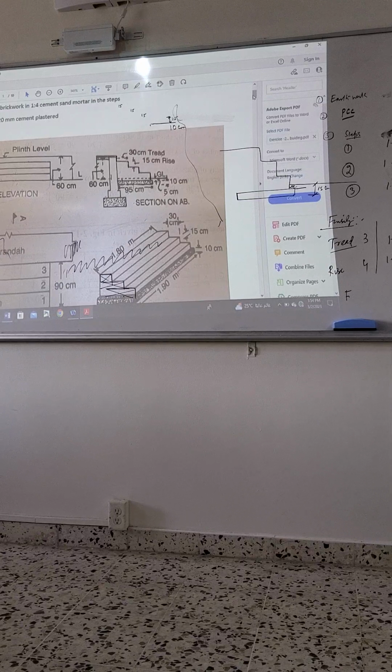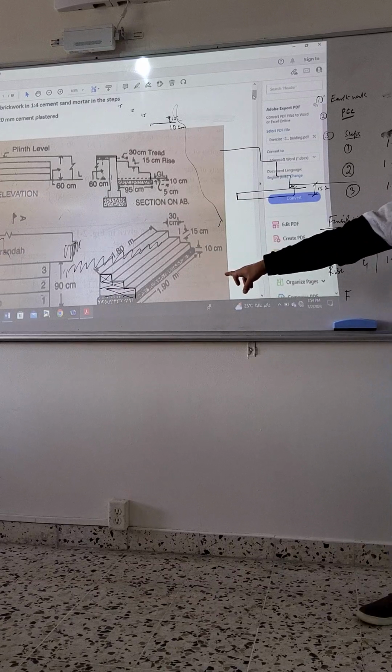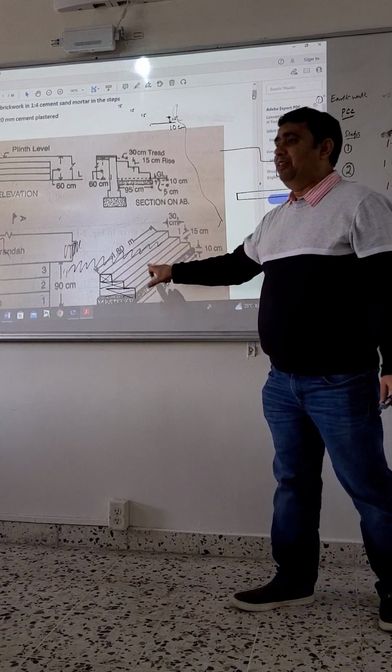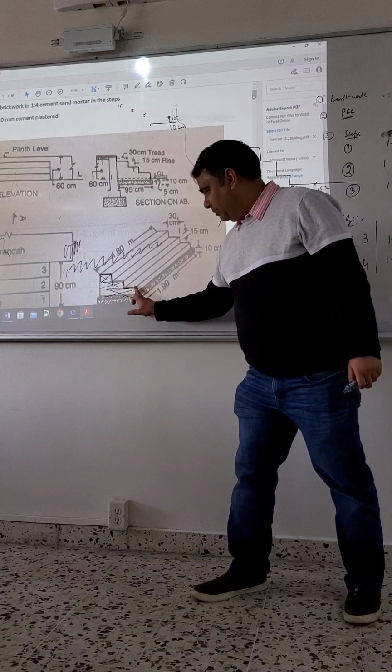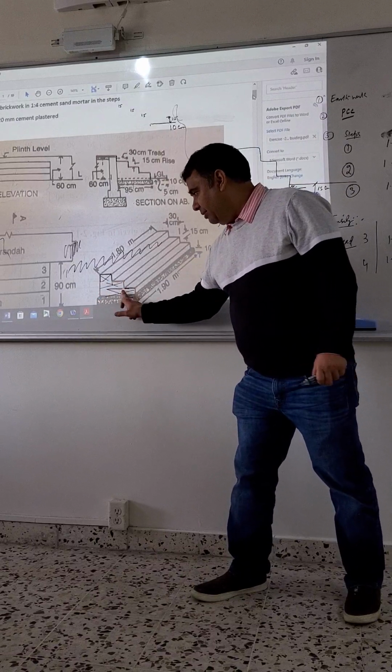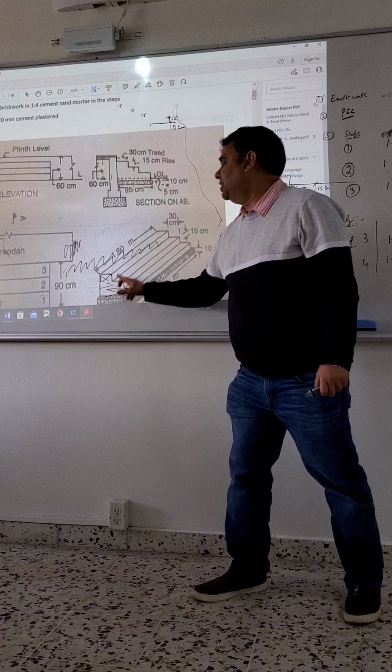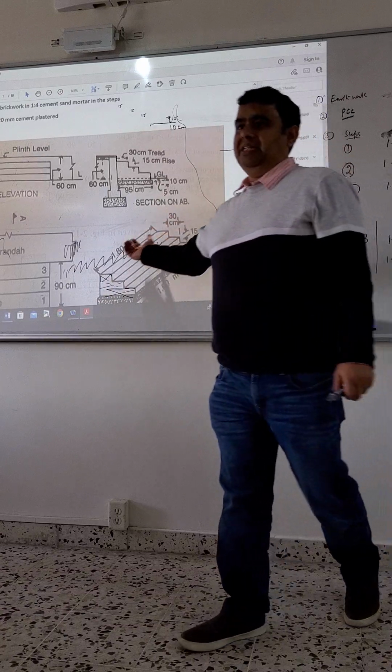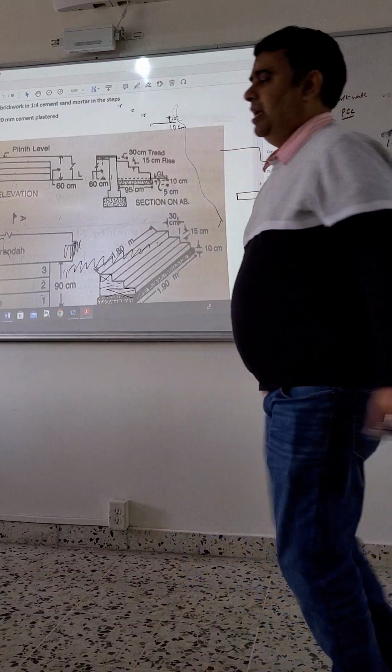No, it is not similar for this step. This is the concrete quantity, in cubic meters. This one is the area, so it is square meters. Remove the length from here. So this length multiplied by this length multiplied by this length multiplied by this, and multiplied by 2 for the other side. And the depth will be 0.15.